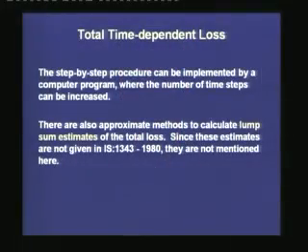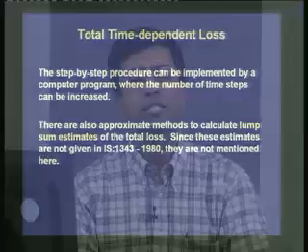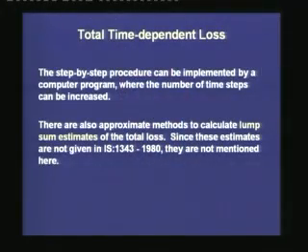There are also approximate methods to calculate lump sum estimates of the total loss, which consider the interaction of the creep, shrinkage, relaxation with the drop in the pre-stressing force. But since these estimates are not given in IS 1343, they are not mentioned here. In case somebody is interested in using these methods, then they can use the methods recommended by the PCI committee or which are published in some recognized publication.